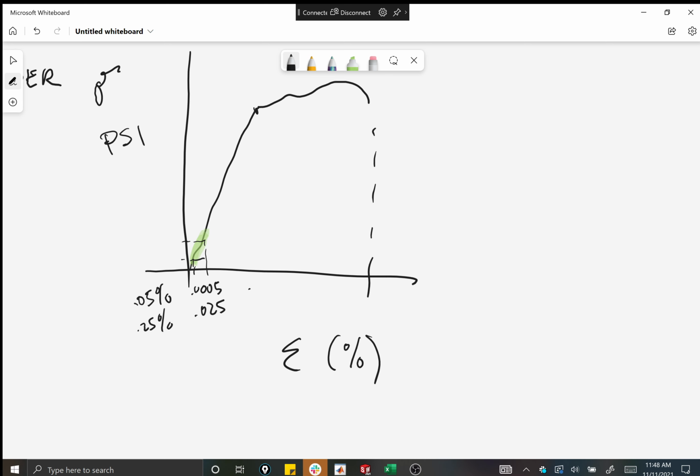We also need a standard. We need to say, this is going to be brass 260. There's a certain way you have to manufacture that. And when you test it and tell us what the Young's modulus is, you measure that between 0.0005 and 0.025 strain, and everybody does that. Then we're comparing apples to apples.